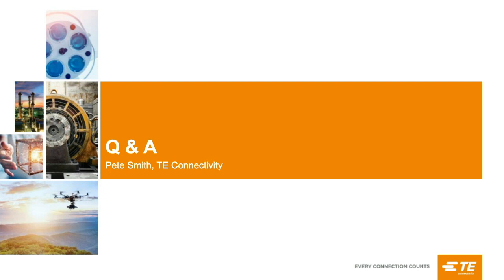We have a design, we call it our microfuse design, where the front end of the sensor is a single piece of steel. There's no welds, there's no O-rings, there's no mechanical features that could fail under high pressure. It's all a single piece of steel that we machine into a very specific shape. And then we can add sensing elements to it in ways that the sensing elements are not exposed to the liquids, but they can measure the pressure of the liquids very accurately.